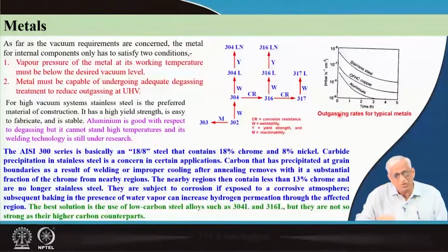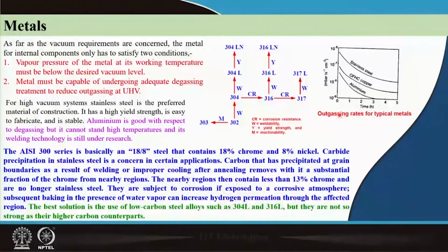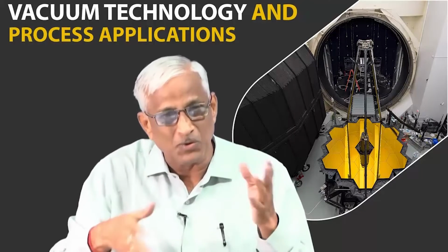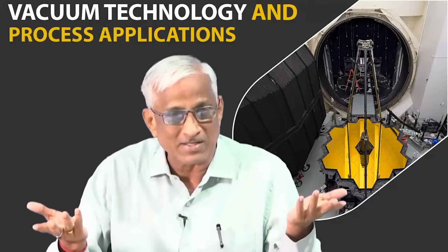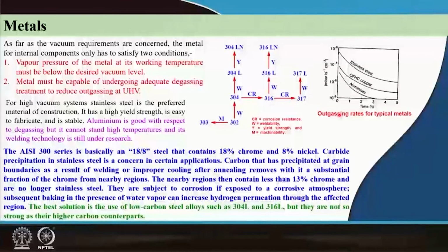That is a real problem only in ultra high vacuum. Up to 10 power minus 6 torr, surfaces matter. That is the reason even if you use mild steel, if you are able to make some specialized treatments or platings, you can use it up to minus 6 torr maybe, if you can handle the corrosion problems. But stainless steel is definitely good because of corrosion resistance.